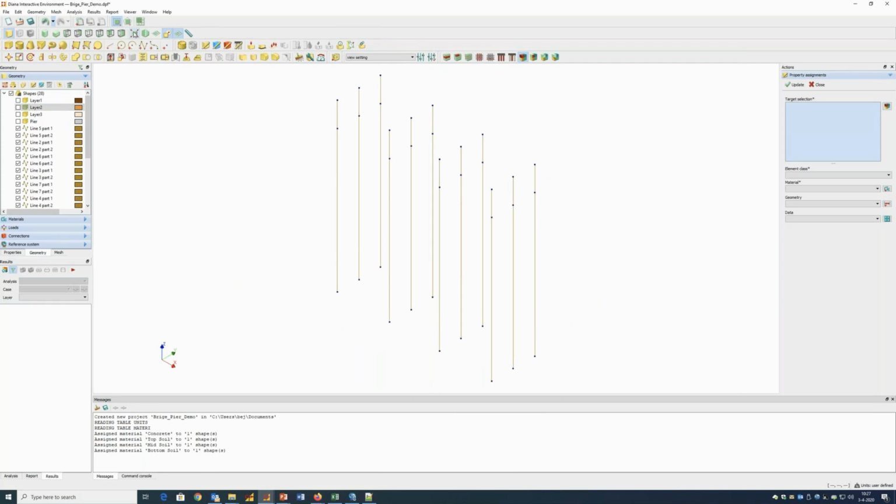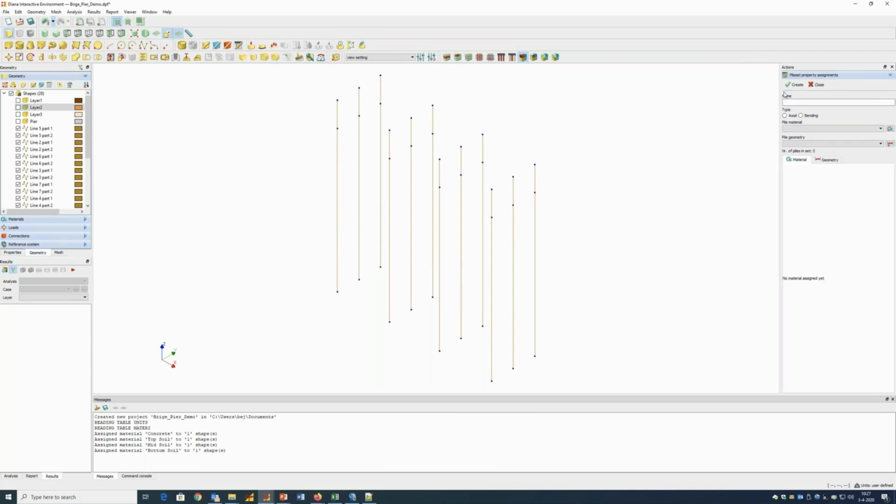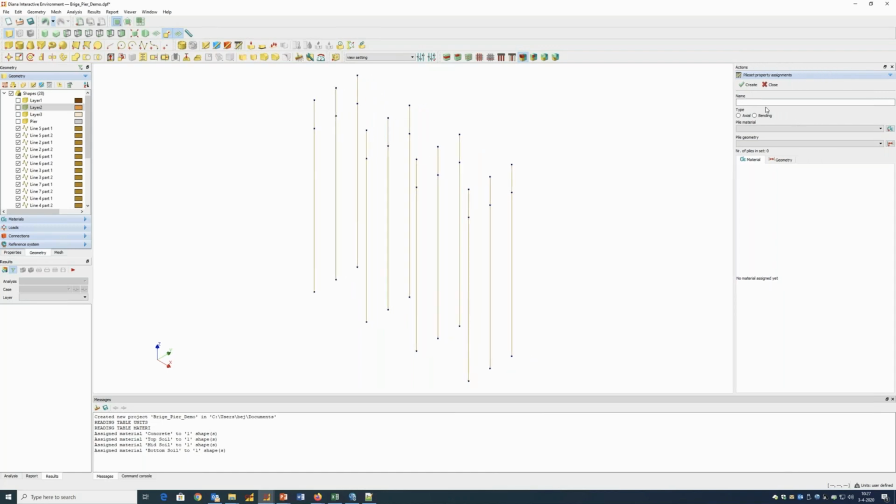And now I'm going to deal with the pile. So, as I mentioned during my presentation, we have a pile wizard for that. I'm going to expand it a little bit. And how it works: first, you create a set, and I'm going to make 2 sets. So pile in concrete and pile in soil. And I'm going to upload the existing material, so my pile in concrete that I imported.